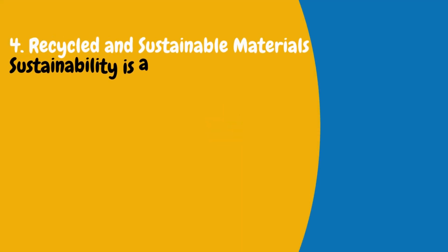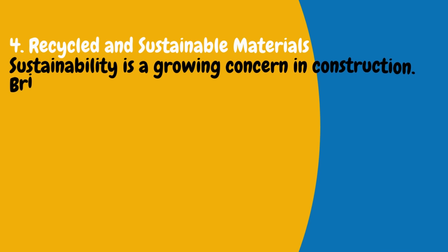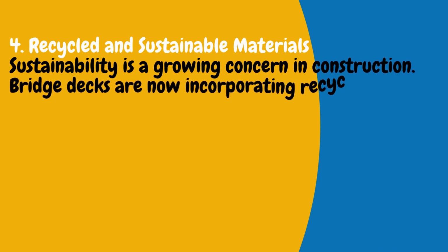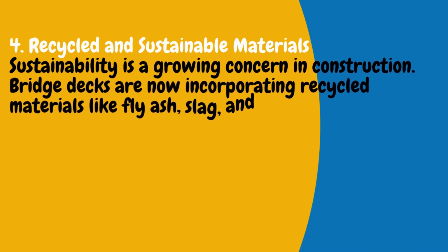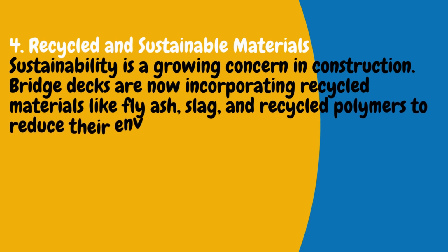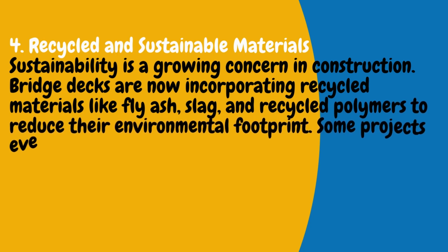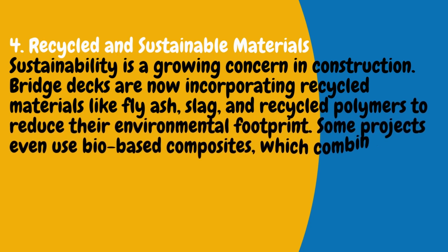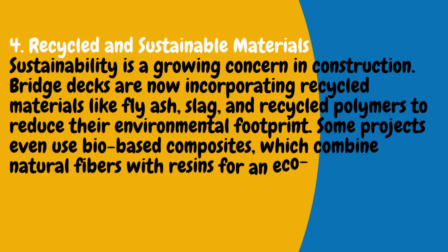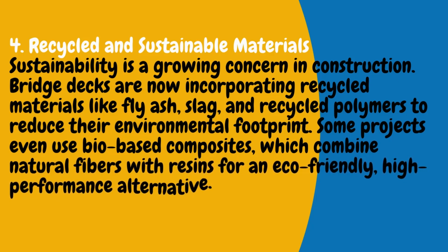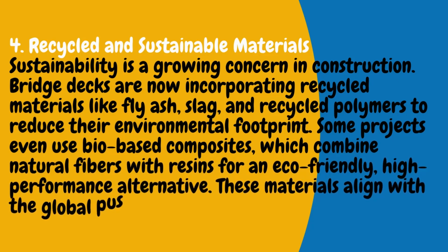4. Recycled and sustainable materials. Sustainability is a growing concern in construction. Bridge decks are now incorporating recycled materials like fly ash, slag, and recycled polymers to reduce their environmental footprint. Some projects even use bio-based composites, which combine natural fibers with resins for an eco-friendly, high-performance alternative.